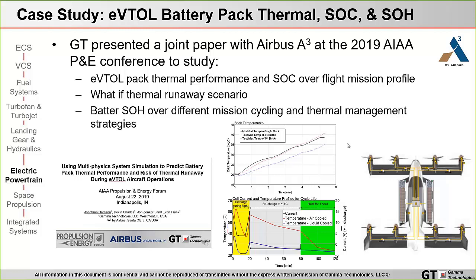And then this could also lend itself to state of health monitoring, taking into account different mission profiling, where you might discharge over a given notional flight mission profile and then recharge a battery at a given C rate and then rest and so forth. Depending on the cycle profile that you put in, that can determine how long your battery will last, and what type of thermal management strategy you would need to have the battery last as long as possible.